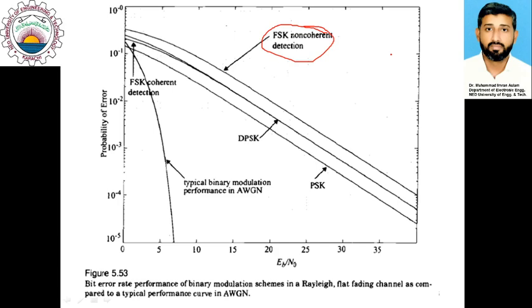Secondly, this is FSK, so the information is represented in frequencies. At the receiver side, you only need band pass filters of a specific band in order to extract the original information.